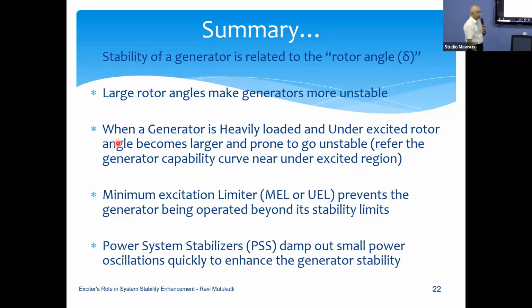Adding a power system stabilizer can greatly reduce the chance of the system or the generator going out of synchronism. And I think I did not add the statement saying that you need to have proper coordination between protection and the limiting, in order to operate the limiter first rather than the protection tripping the unit.